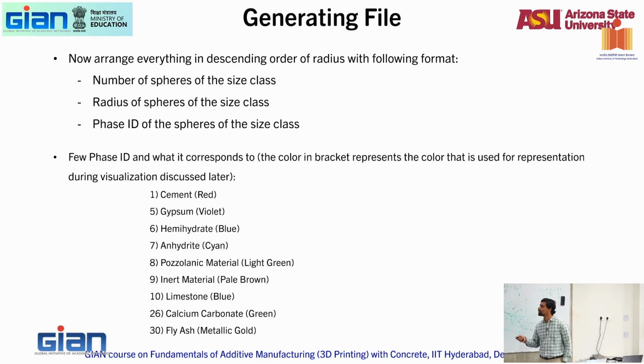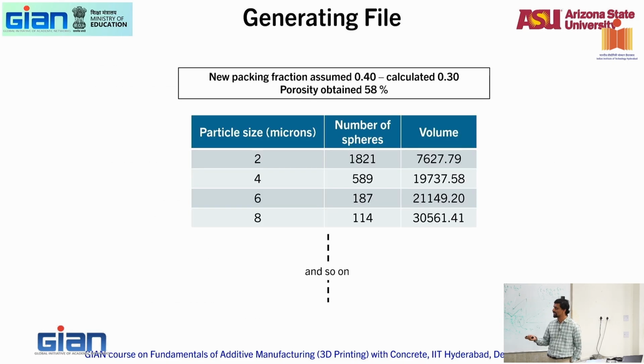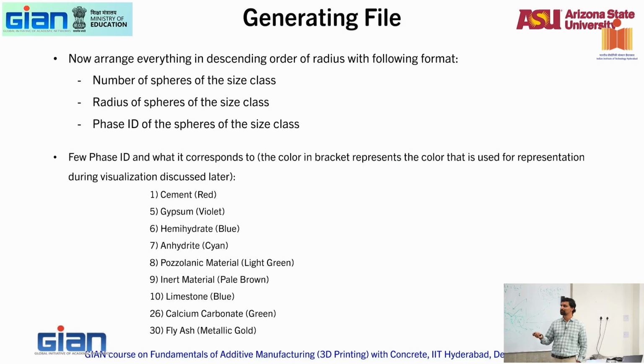But again, these are the volume fractions, right? If you see, I'm giving them to you in ascending order. But the input file takes it in descending order. And descending order itself, right now I'm talking in terms of one single particle, OPC. Now, if you have limestone, the descending factor comes for limestone too. Meaning if you have an 18 micron OPC and 18 micron limestone, you have to select the OPC first,